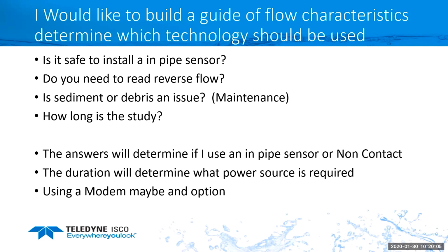And then, how long is the study? If you're only going to be out there for 10 minutes doing a spot check, then we're not so worried about the sediment or surcharging because you're out there on site. So the answers to these are going to determine what technology I use, if I'm going to use an in-pipe area velocity sensor, or if I need to use a non-contact one because there's surcharging.